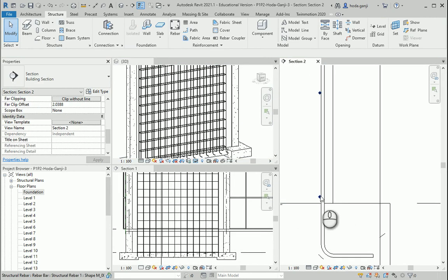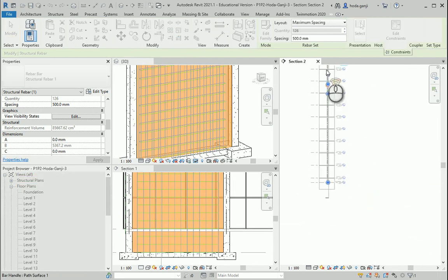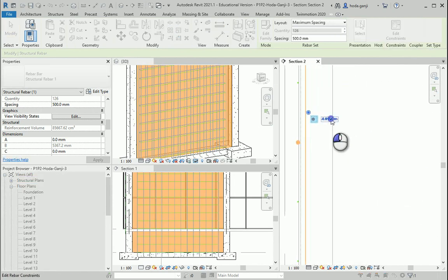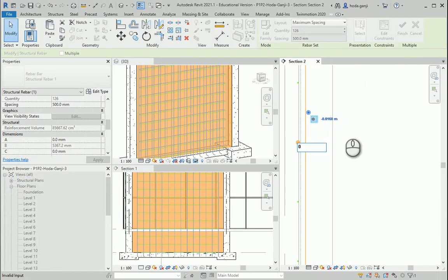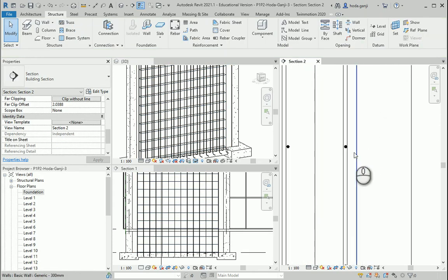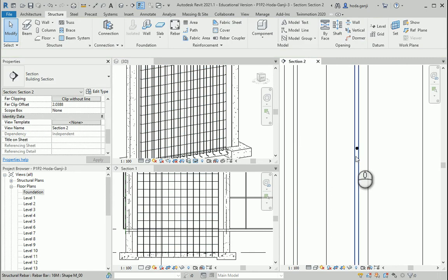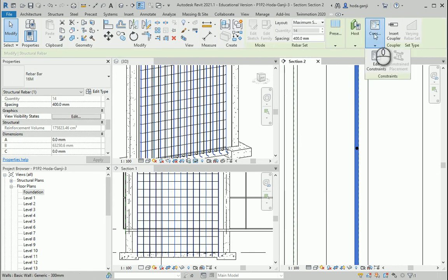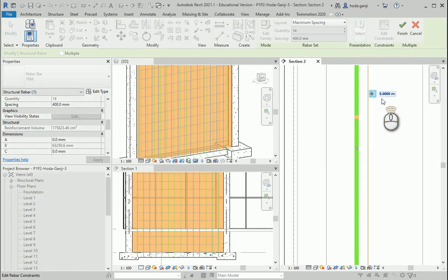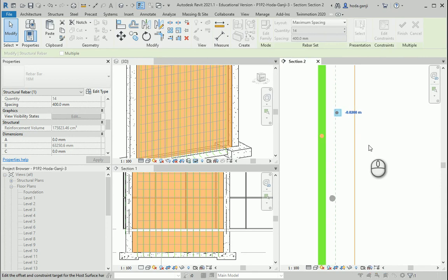Actually, I want to change the constraints here. I want to set this to 0 and move the other one inside because that would make more sense. I will delete this and I will actually mirror these ones again. And for the constraint here, I will assign the negative value to this one instead. So it's going to be negative, like 0.02 maybe.